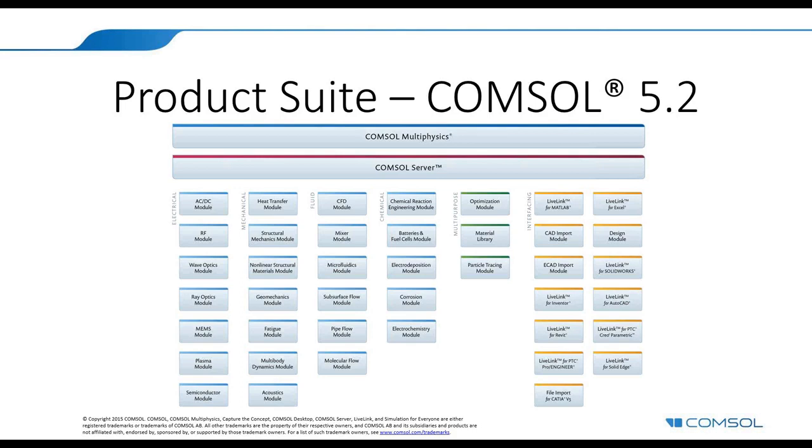And when it comes to very large models, then it's good to know that COMSOL Multiphysics supports cluster computing, so you can run computation remotely on clusters, and we support a wide range of clusters and operating systems. So I would recommend, based on your needs, to get in touch with COMSOL and get a recommendation. But the starting point is a good desktop computer with some RAM and some cores to perform the computations.